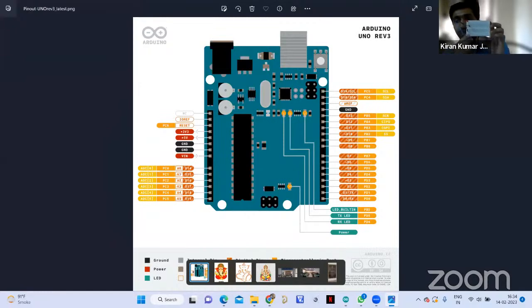As you can see, I have connected this one. While doing this, I'm taking a common 5 volt and the ground. I'm taking 5 volt from this one, so you can see I'm taking the positive part of this. I am taking the positive, which is 5 volt, and the ground. So I've connected this. As I already connected the IR sensor, let me connect with the Arduino, the microcontroller itself. Let me show you how I'm going to connect.